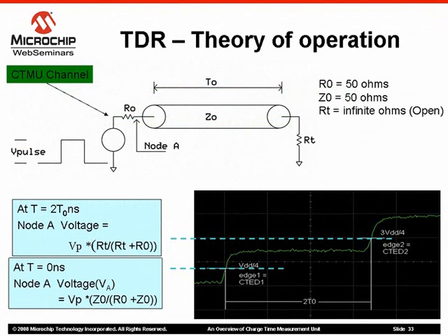First, let us see what the time domain reflectometry or TDR is. In layman terms, TDR is basically time taken by a pulse to propagate through a circuit and to reflect from the end of the circuit back to the source. In example of a coaxial cable that has 50 ohms, it is typical time domain reflectometry. TDR has long been used to measure the electrical length of transmission lines, locate faults in transmission lines, and characterize transmission line impedance.